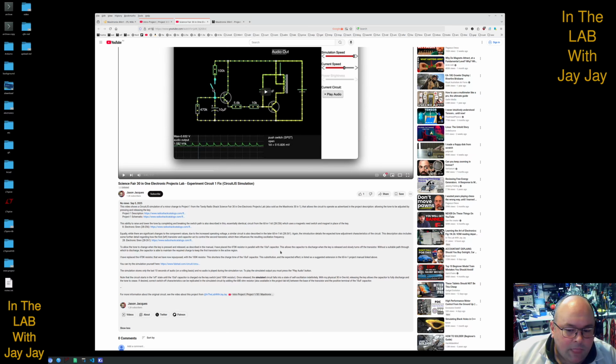Once released, the simulated circuit falls into a state of self-oscillation indefinitely. With my physical 30in1 kit, pressing the key allows the capacitor to fully discharge and the tone to cease. If desired, correct switch-off characteristics can be replicated in the simulated circuit by adding the 680 ohm resistor, also available in the Project Lab kit, between the base of the transistor and the positive terminal of the 10 microfarad capacitor.